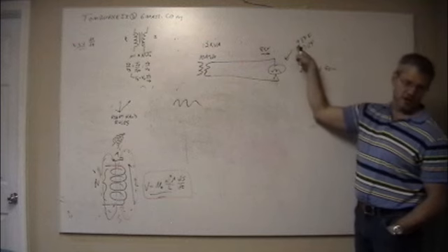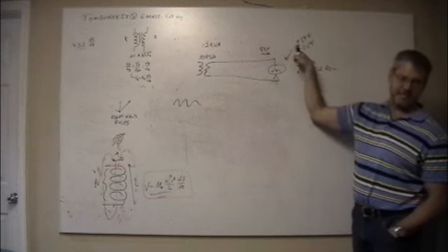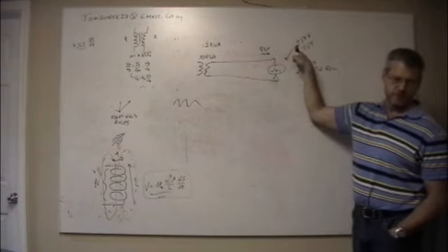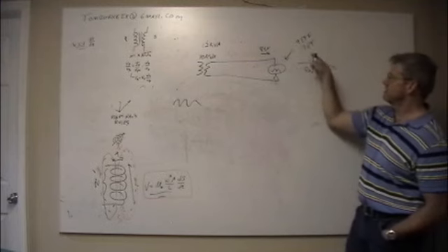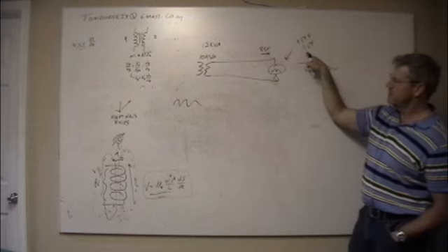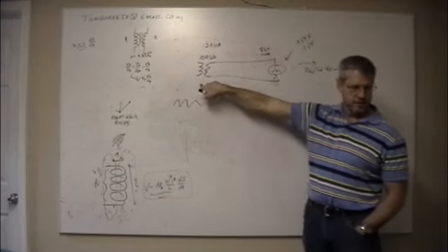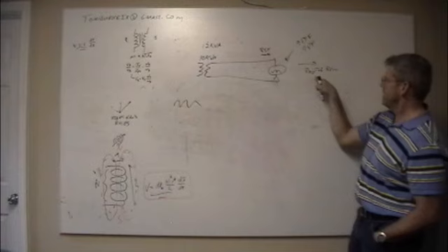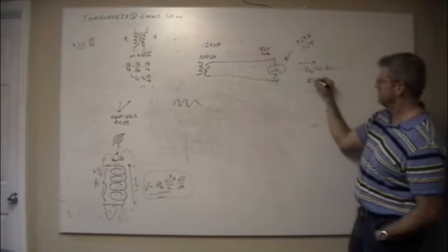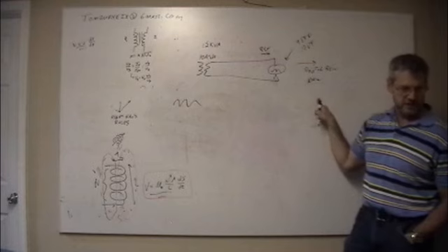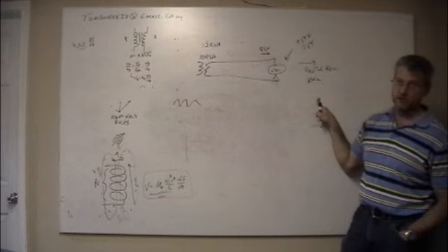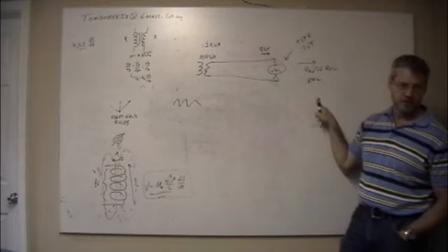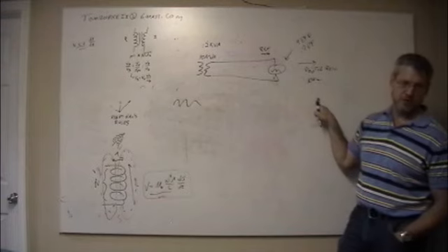I mean, I'm getting closer to a good wound motor will give me 90-95% efficiency going through. Most of the losses are mechanical, and my power efficiency is getting the same, but because I'm at 0.7 power factor, I'm really driving this guy hard. So if I want to say I've got a 10 kilowatt load here that I really need to drive, 10 kilowatts is about 749 watts to a horsepower. So that's about 12 or 15 horsepower.